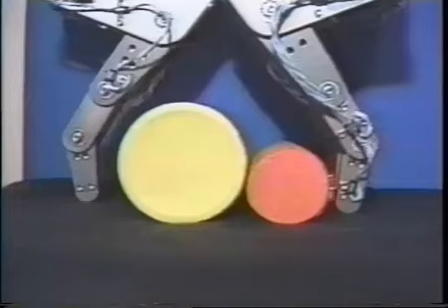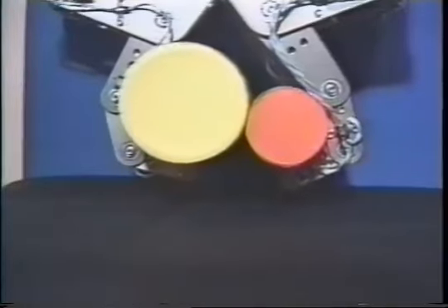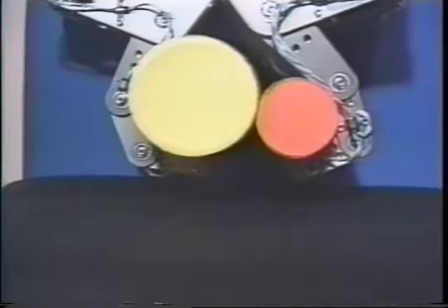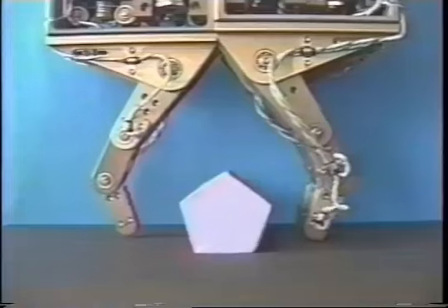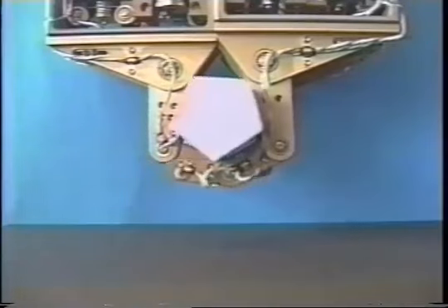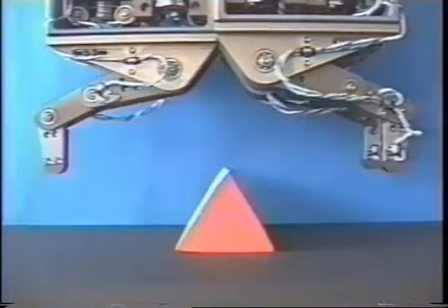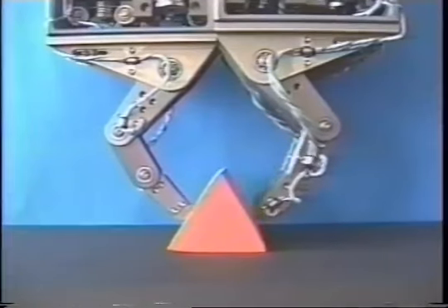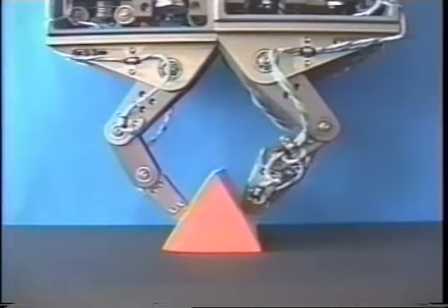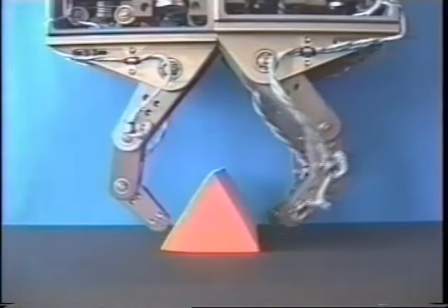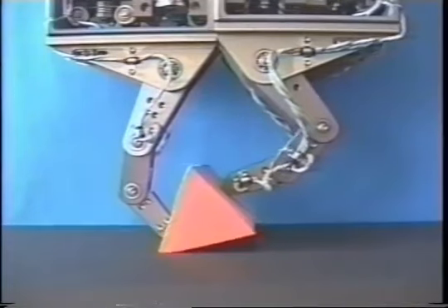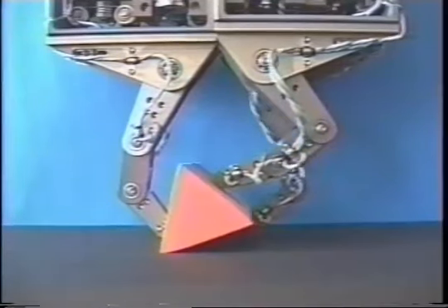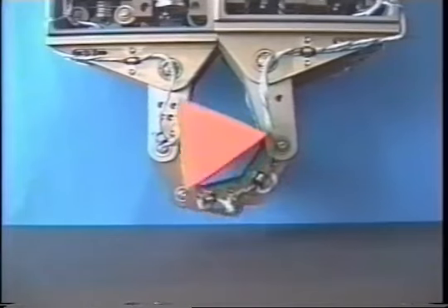The enveloping grasp can also be achieved even if there is more than one object. This grasp procedure is also available for a polygonal object. For the object whose cross-section is triangular, however, the wedge effect can no longer be expected. For such an object, the robot finger automatically switches into the rotating motion-based grasping procedure.